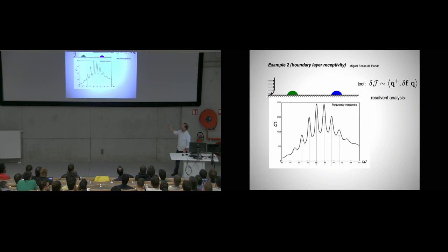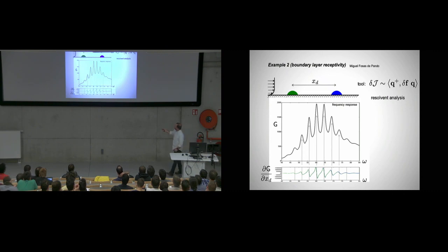Then we say, okay, how about changes in the Mach number? Well, we take all the terms that have Mach numbers in it and multiply it, and so on and so on. So what we did is we wanted to know if we change the distance between the two bumps, what will happen to this curve, the amplification. And usually what you have to do is you take the bump a little bit further, you do the whole calculation again, and then you get a second curve, and then you see how that second curve changed. But since we have the forward and the adjoint problem, we have everything we need.